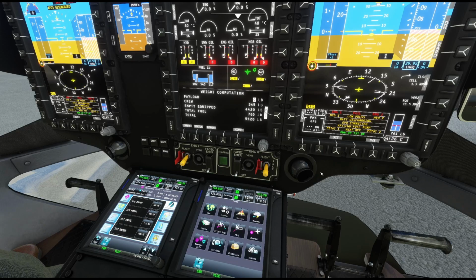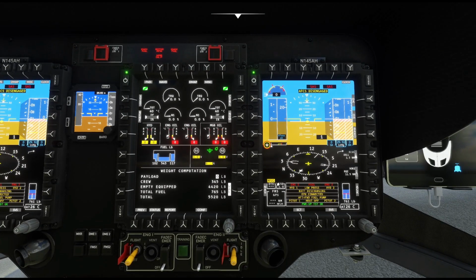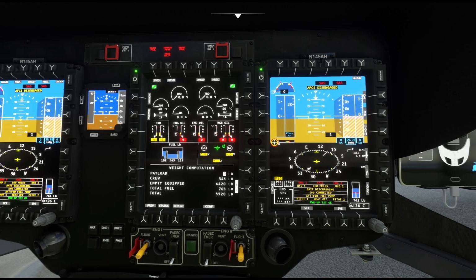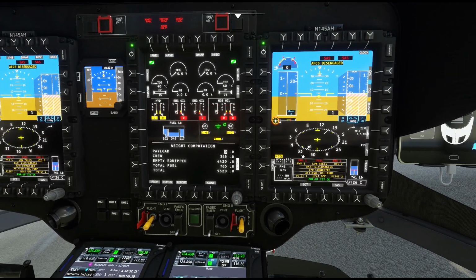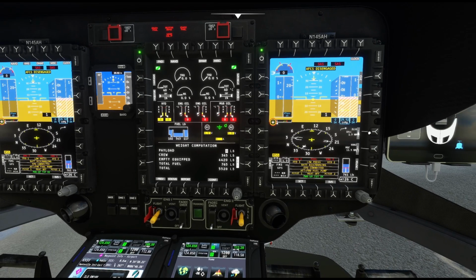All right, so now the FMS does not have anything in it, so now we're back to white on this. So these values right here are simply things that I have pointed. So I'm going to put this to the ILS coming from 1. So the ILS to Huntsville is on 1. The VOR from there right here is on number 2. So you can have both of these up at the same time. So you can tune 2 different VOR stations and do the whole intersection thing when the 2 stations cross at a certain point. Then you know where you're at.